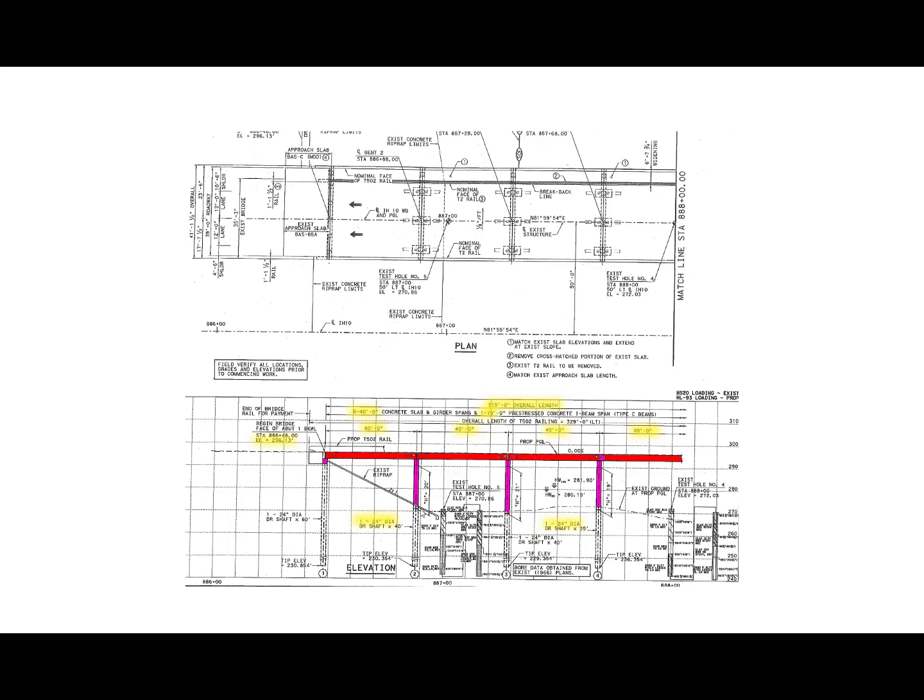Back on the construction drawings, we'll look at the bridge deck information to get the geometry that we need to model. I've highlighted the bridge deck in red. Everything that's pertinent for modeling I've highlighted in yellow. It's a 315-foot long span. It's composed of 6 40-foot girder spans and one I-beam span, which is 75 feet long. The elevation that starts the bridge is noted as 296.13, and it's a 0% slope, so it's flat across.